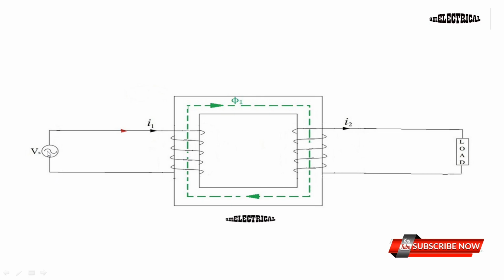As soon as we connect the supply with one winding, I1 starts flowing through N1 and flux phi1 is produced, which happens obeying Ampere's law. Now the phi1 flux is flowing upward, which is in accordance with the right hand thumb rule. And on the secondary side, E2 EMF is induced by Faraday's law of electromagnetic induction. This is the overall idea. Now we will discuss them one by one.